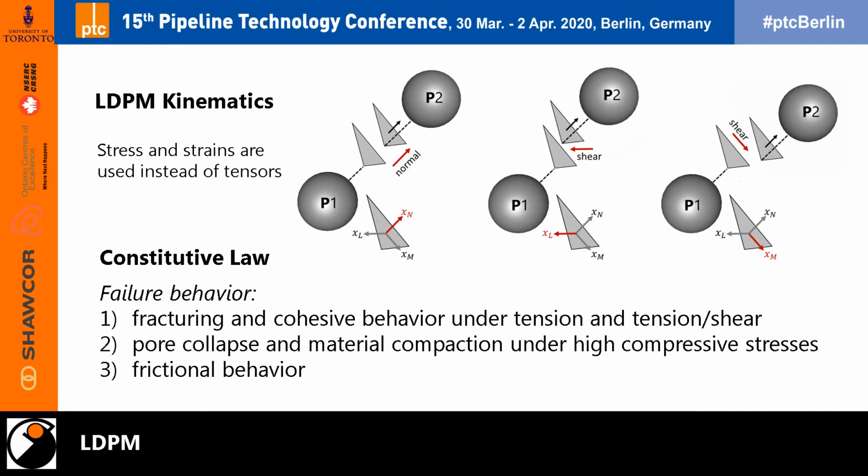LDPM stands for Lattice Discrete Particle Model, and it simulates the mesoscale concrete behavior. LDPM calculates the displacement between the aggregates, where there are three directions of displacement: tension between the aggregates and two shear directions. From the displacements, the stresses and strains are calculated.